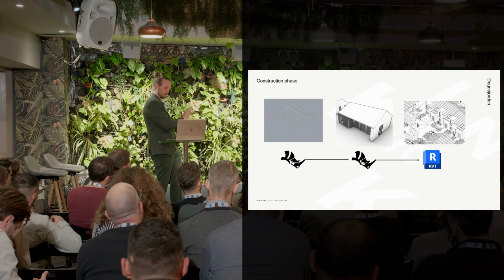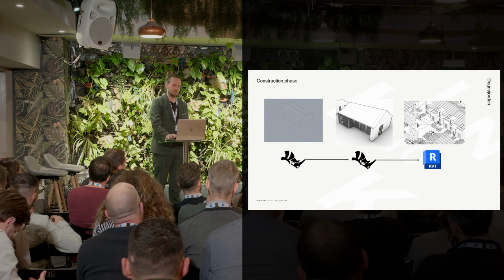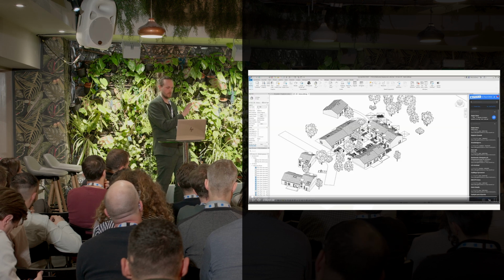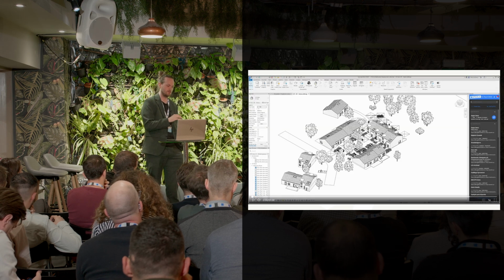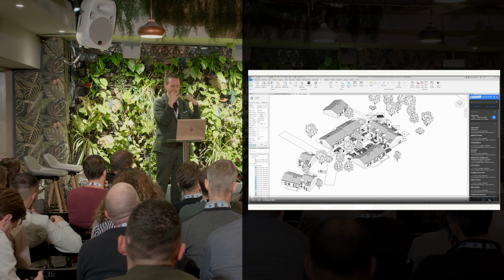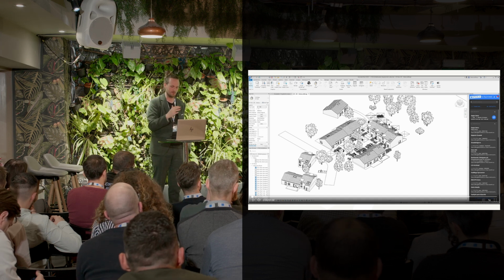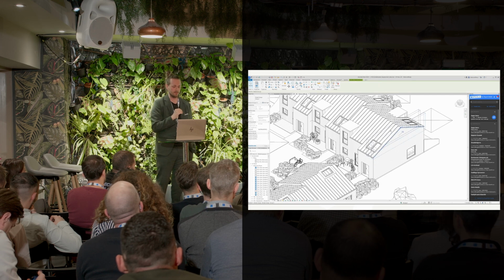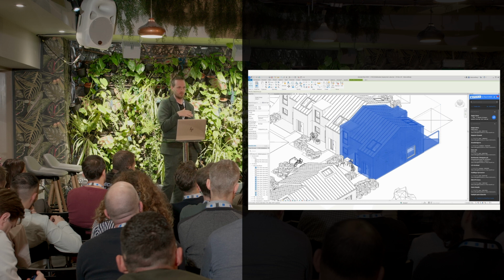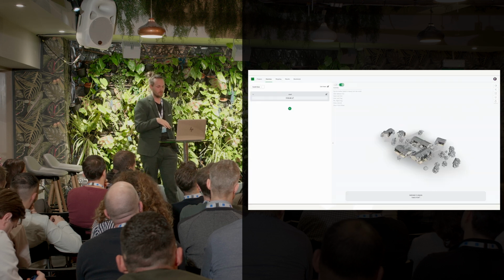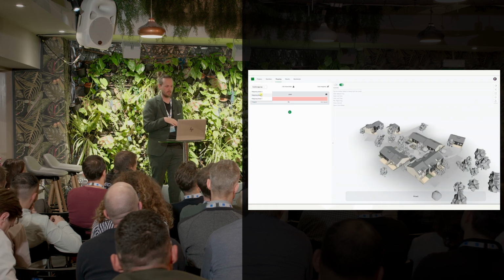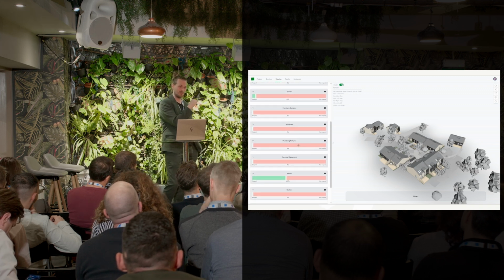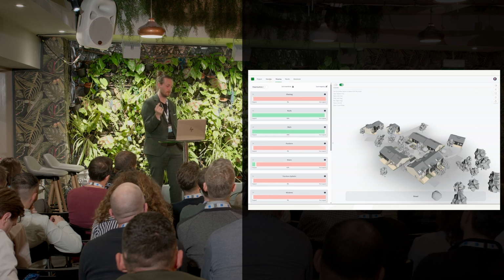So the final step in this project was that we moved it to Revit and did our detailing there, and they coexisted for quite a while. So it's not like 1, 2, 3, but more like 1, 2, a bit, and then 3. We take all our geometry from Revit, and Speckle takes everything, so we can have our model groups exploded automatically for the application, and we're not really caring about the data structure that comes into Speckle because we're checking it on a per object basis and then creating our own structures.